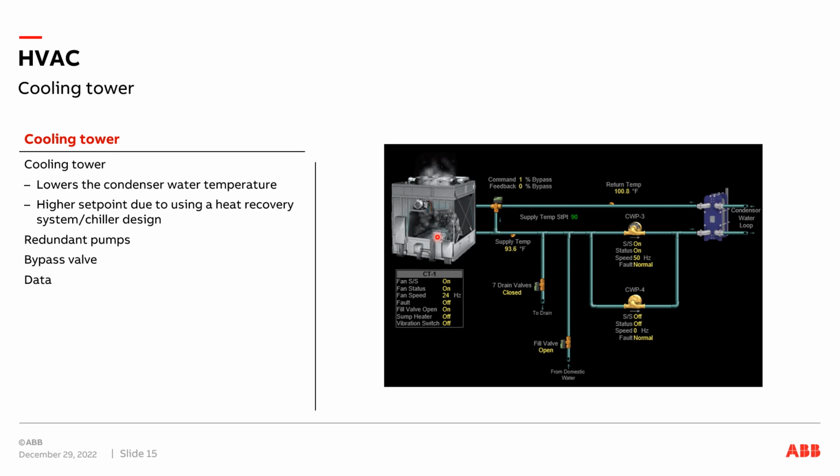A lot of times just going down the waterfall is not enough to cool it to what your set points are, where you're targeting. So that's where this fan kit comes into play. There's a VFD on that fan, and it'll ramp that fan up to faster and faster speeds based on trying to hit that set point of water temperature. With that fan going full speed, you'll get a lot of extra evaporation, which causes more of a temperature drop. If that fan is running slower, there'd be less evaporation. So it's all about trying to hit these set points.